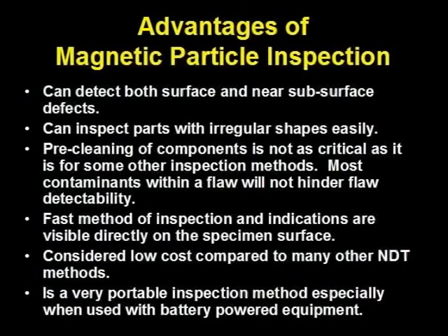The AC excitation continuously reverses the magnetization direction, while the field strength increases and then decreases as the part enters and leaves the coil. Another method is to use the head shot repeatedly, changing both the direction and strength until the magnetism is removed. Magnetic particle inspection has the following advantages.